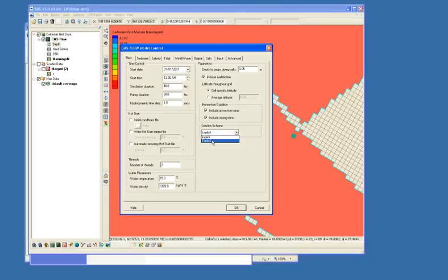The explicit solution scheme is really what we first came out with. It has limitations on current, and so your time steps are pretty small, from anywhere from 2 seconds, and we've had some cases where we needed to bring our time step all the way down to, say, 0.25 or 0.2 seconds, and it makes the length of time for these jobs to run extremely long. It's hard for us to work with.